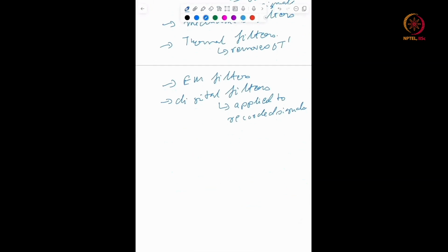So another approach to reduce undesirable effects is compensation. By this, we understand the deliberate introduction of additional interfering or modifying inputs, which may partly or entirely cancel the undesirable effects. For example, if you use compensation, I'll give you an example, which is the case of a strain gauge. The strain gauge works on the principle of a Wheatstone bridge. So in the case of a strain gauge, the output is sensitive to ambient temperature fluctuations.